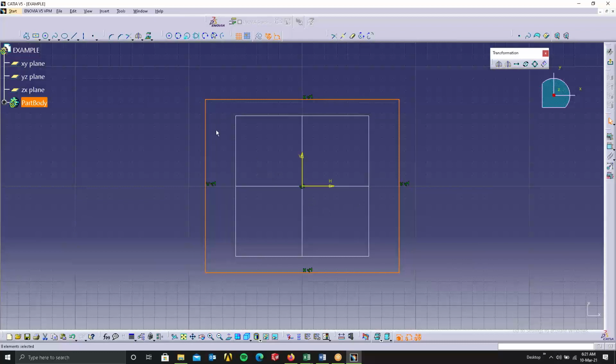Then we have used normal drill holes. We have not given taper holes or anything, because if we give taper holes, then we'll have to use an electron beam laser drilling machine. That will be very expensive. Again, it's very rare and difficult to find vendors, so we have to spend more time searching. Sometimes the vendor will be in Mumbai or somewhere, so we have to take the product from here to Mumbai. It's time consuming, cost intensive, and very risky because we don't know if it will come out properly or not. So I give normal holes in these locations. So we can do it like that. Are you understanding? Okay.